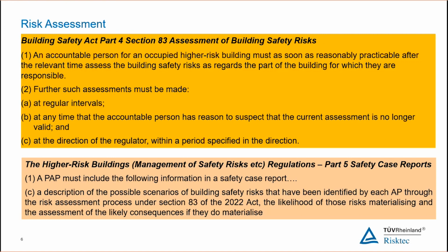So this places a couple of specific requirements on us. One, we have to do the risk assessment, but also this is a through life obligation. We have to make sure that our risk assessments, our understanding of how we manage the risks in our buildings, are fit for purpose when we first do the risk assessment and start operating, but that we go back and revisit this on a regular basis to make sure that it continues to reflect reality.